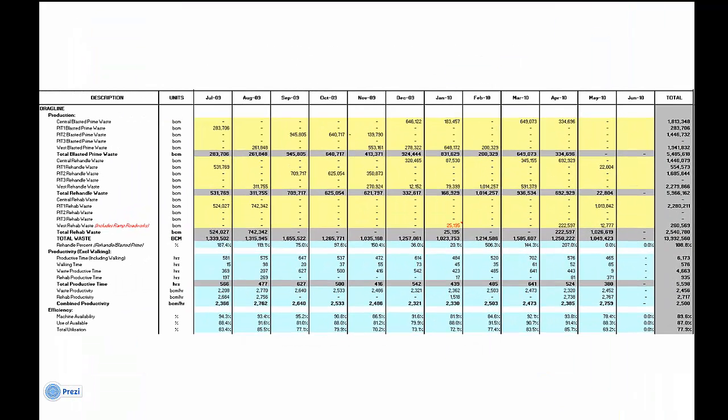The reconciliation should include planned versus actual numbers, like dragline volumes, both prime and rehandle, any cast or dozed prime volumes, any excavator prime volumes, the dragline dig hours and non-operating hours, the dragline dig rate and payloads to ensure that they're not going over the RSL, and also any comments about the strip design or other problems that may have arisen during the strip operation.